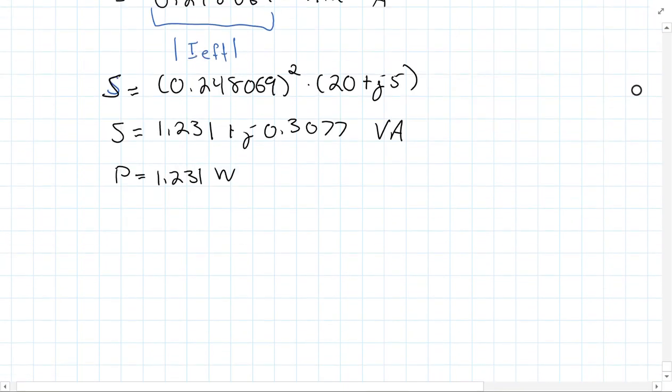So the key thing here, just to end, and we'll star this here, is that for max average power transfer, you need to set the load impedance to the conjugate of the Thevenin impedance.